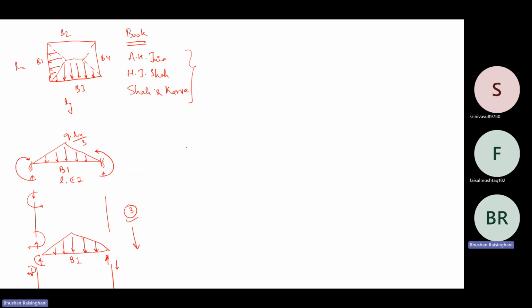Now, this is transferring of load. Second is what load to have for the maximum and minimum bending moment, which we call the substitute frame method. Right. In undergraduate, we had done the substitute frame method for gravity and the portal method for the lateral loads and moment distribution also for the sway frames. The same we have to utilize here. And in the substitute frame method, how many internal and external supports are there?